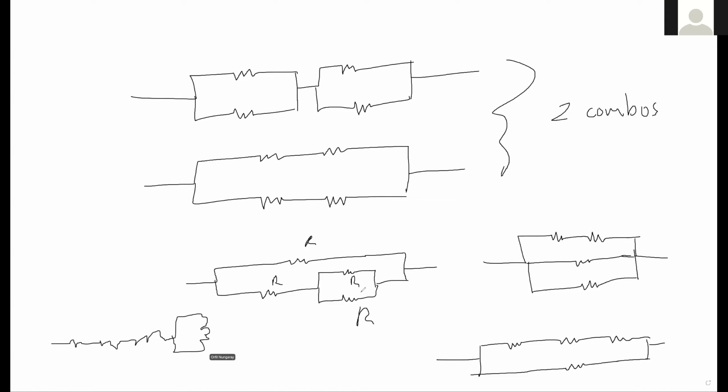So pretty much I have a resistor here, resistor here. Okay, I see it. And then one right here. Yeah, this last resistor there is shorted out. So this is not a valid combination here. Oh, it's shorted out? Yeah, if you connect the resistor back into the same point here, then it doesn't contribute to anything.